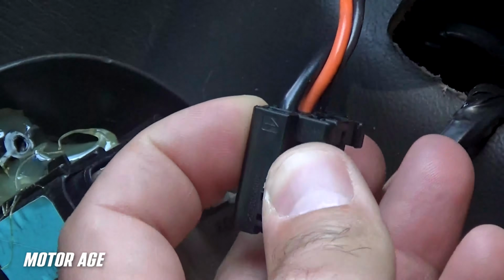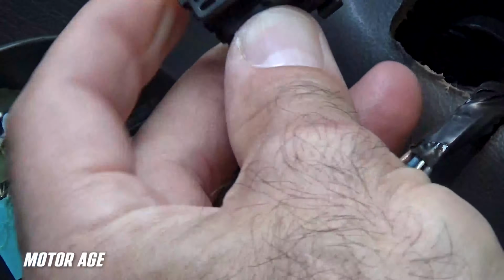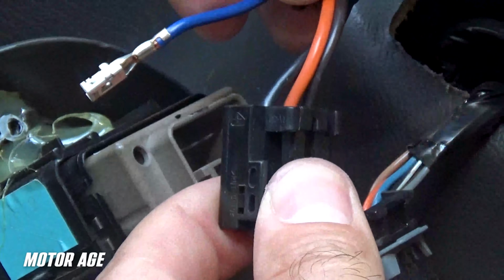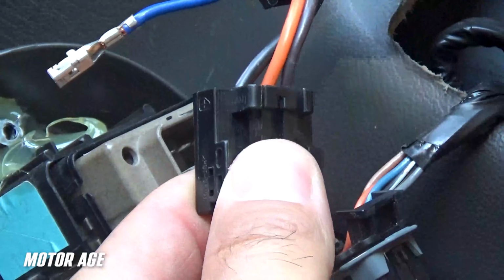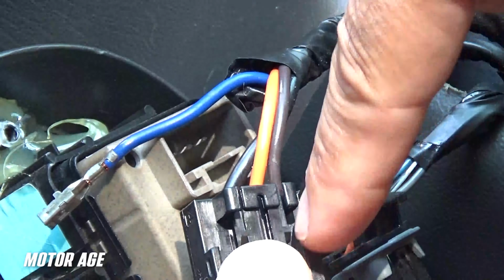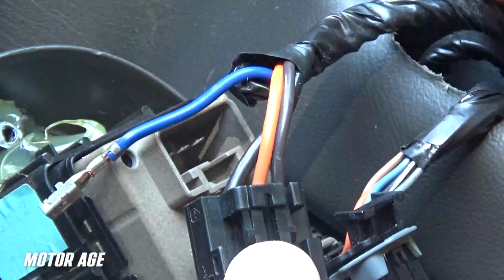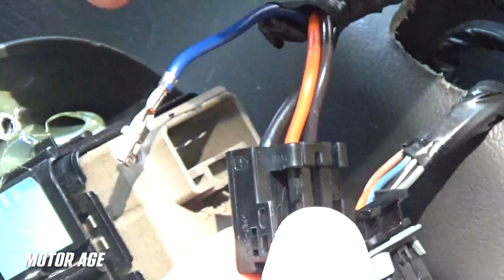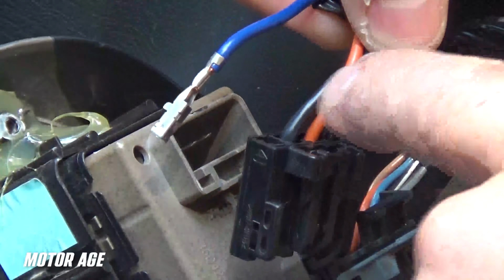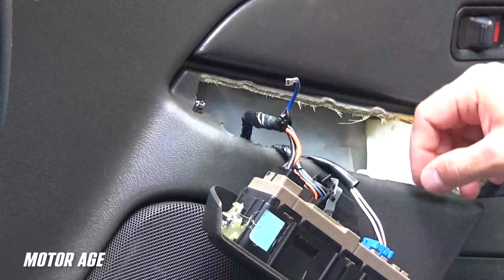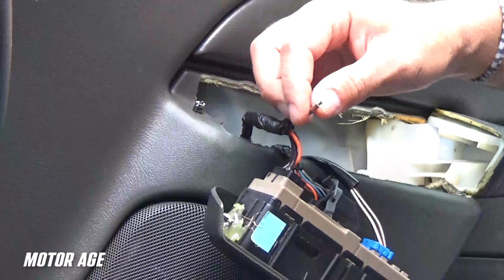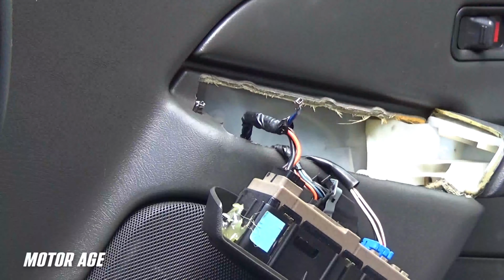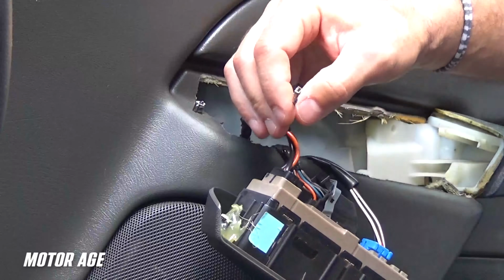What can be seen is the blue wire had become disconnected or unmated from the connector. That connector position assurance tab was not secured properly. What that means is voltage command from the switch came in through the brown wire, made its way out to the power window motor assembly, went through the motor and made its way back towards ground through the blue wire. But since the blue wire was not coming in contact with the switch assembly, it couldn't reference ground on the black wire. After close examination, it's determined that this terminal has been spread, meaning the contact between the male and female are not occurring. So what we're going to perform next is a bypass test.